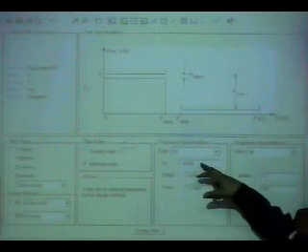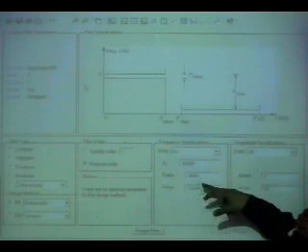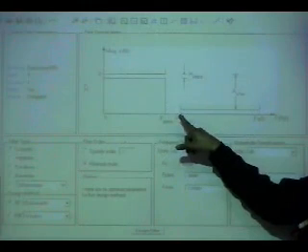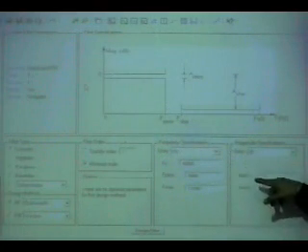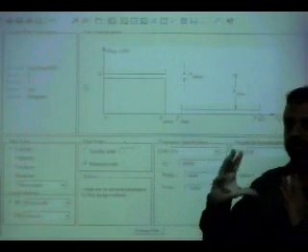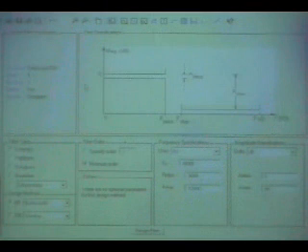So if 2 pi, you can always calculate this and this. So this is omega pass and omega stop, and these are the specifications. If you change these specifications and you say minimum order, MATLAB will try to compensate. Okay, you can change this 80 to 100 dB or to 200 dB. Filter will start getting more and more complex. You change it to 60 dB, it will spend less number of coefficients to give you a filter.